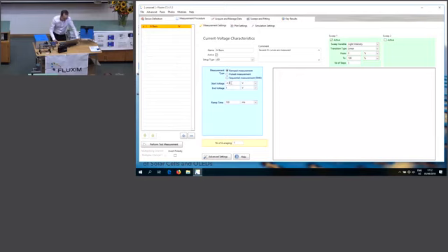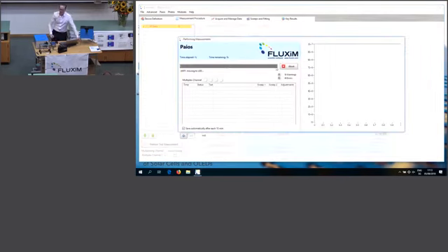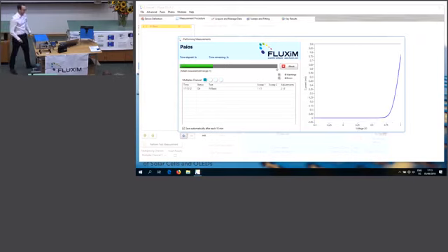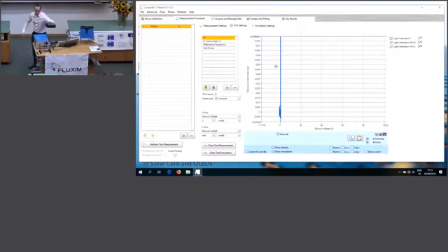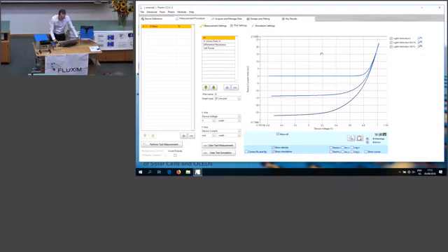So it looks very similar to the OLED, but now it's a solar cell. We measured the voltage from minus 0.5 to 1 volt, and we vary the light intensity. So let's quickly see. You see now it's changing to the LED. Before it used the photo detector, now it's swapped automatically to the LED, and there we go, it starts measuring. So I quickly close here the lid so we have a bit better measurement quality. Oh, and there we go, this is our IV curve.